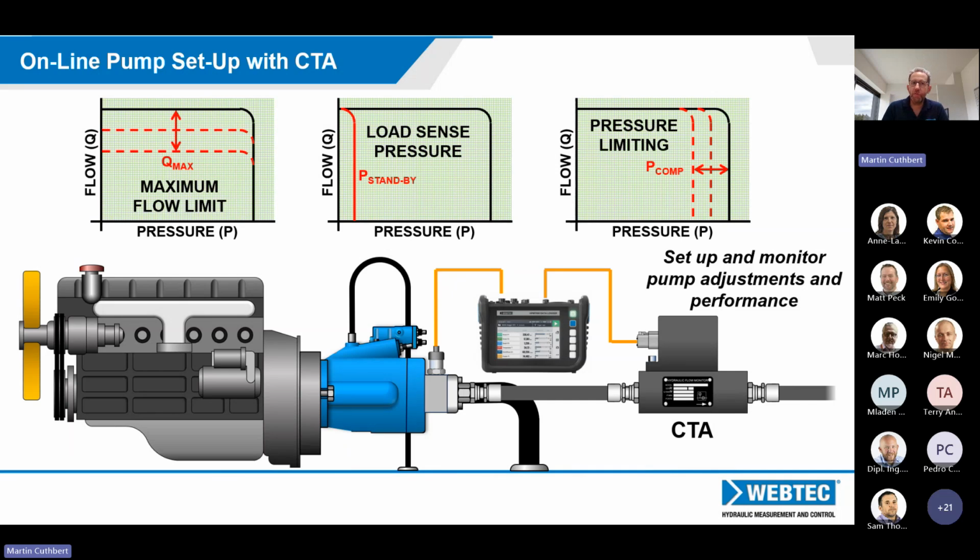That would be a case of a longer conversation, I think. 320 is referring to the viscosity at 40 degrees C, so 320 centistokes. Typically, in most hydraulic applications these would be calibrated around 20 centistokes. So clearly there's quite a big gap on viscosity, and that'd be a case of us doing a deeper dive into your requirements capture: what are the operating temperatures, what's the range, what's the allowable pressure drop, etc. So in principle, yes. In practice, we want to dive a bit deeper into it.